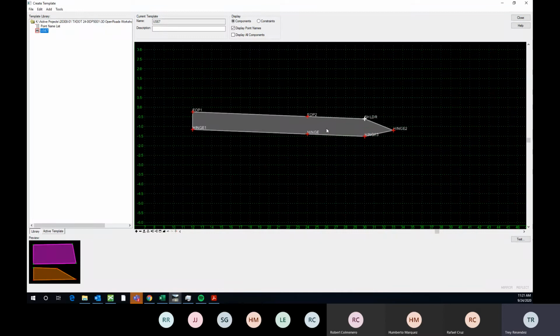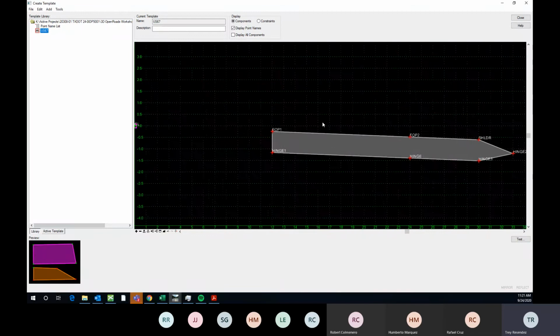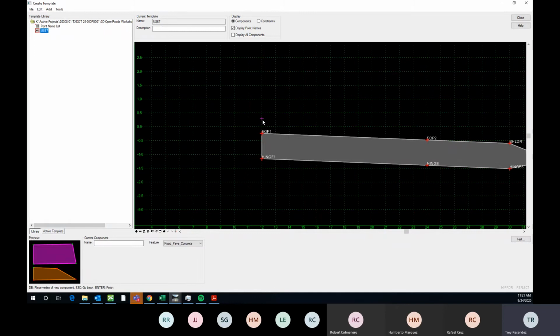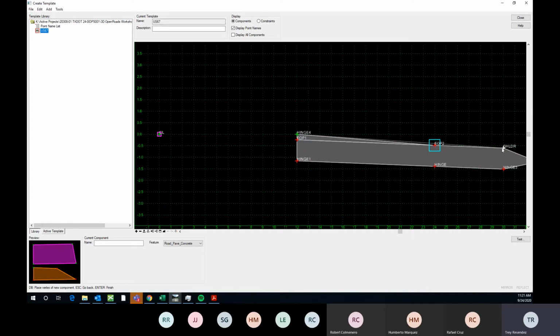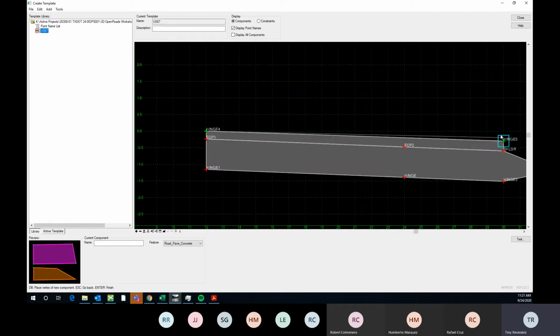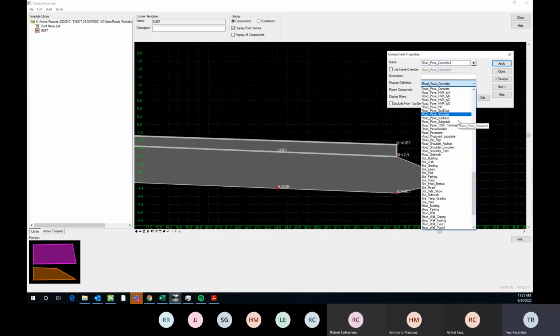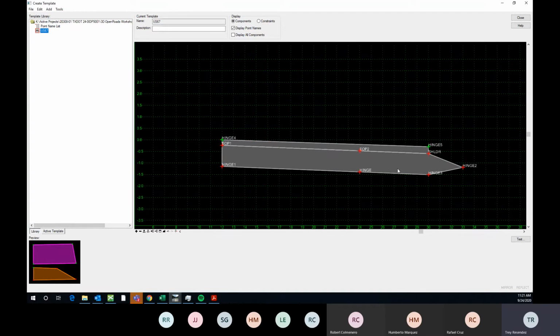So as long as you can build it in here, and let's say we had some kind of layer on top that we wanted, as long as you can build it, and it has constraints, and it has some kind of volume and depth to it, then we can extract quantities. We can change this to whichever feature definition it needs to be, and then once we run the quantity report, it's going to give us the quantities throughout the corridor.